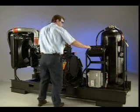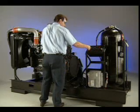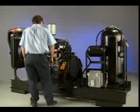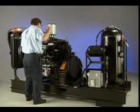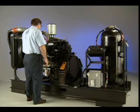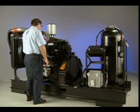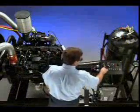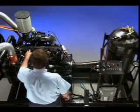A note of caution is needed concerning a coil-on-plug device. These coils have an input voltage of 300 volts and are capable of delivering voltages as high as 40,000 volts. While the coil shock is usually not fatal, the secondary reaction may cause a serious accident. For this reason, it is important for you to take precautions when working around the ignition system to avoid shock. Whenever possible, shut off the engine before performing service.